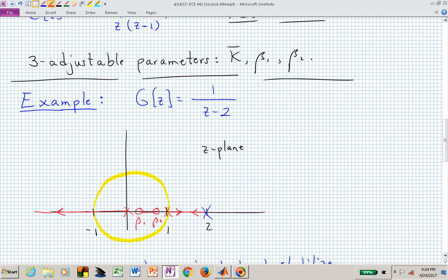The branches between 1 and 2 can't just stay on that real axis segment. They will break away, and they will actually approach the 2 finite zeros, and the pole-zero excess being 1 will now give us an asymptote to 1 infinite 0, and that infinite 0 is at an asymptote of minus 180 degrees.